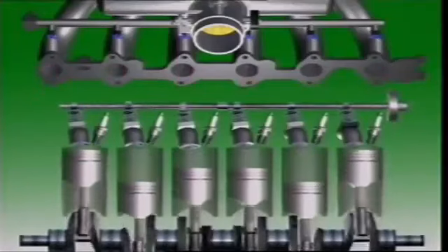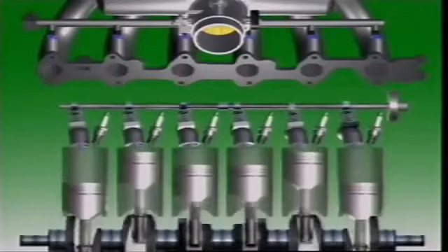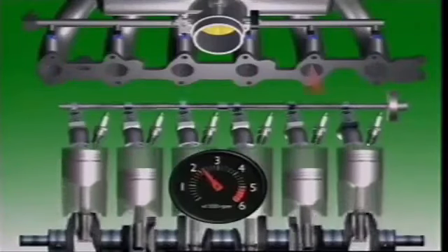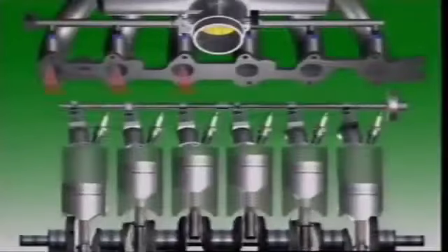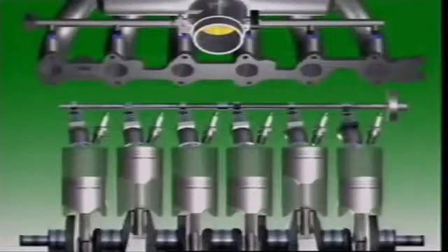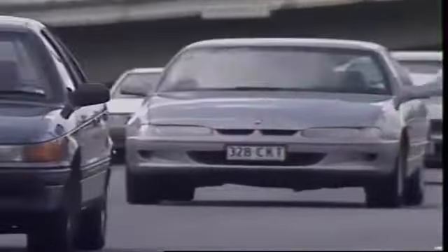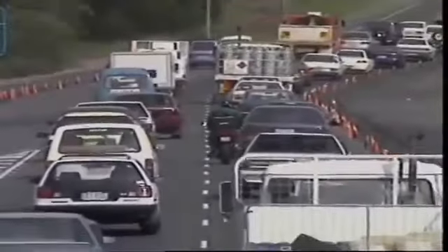In some applications, different modes of injection are combined, so that the mode changes according to the operating conditions. Sequential mode may be used for low engine speeds, changing to simultaneous mode at high speeds. The same principle is used in changing from light loads to heavy loads. Similarly, the mode may change from group injection to simultaneous. Using different modes for different operating conditions makes the most of how the fuel is used, and that improves power output, fuel economy, and emission control.